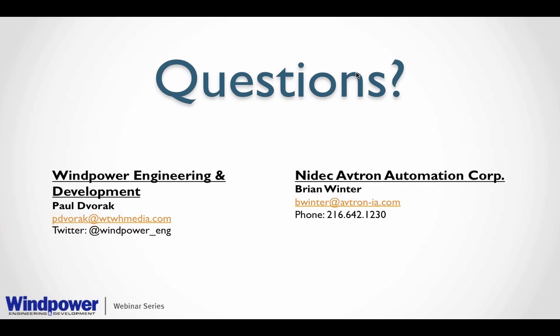Now on the electrical side, the E of EMI, what you want to do is have a design that's actually got a Faraday cage built in. For Avtron, we actually take the circuit boards and wrap them in copper foil. It's extreme because we want to make sure nothing can get in. You can have some extremely powerful radio wave fields. We were familiar with an example where a manufacturer actually installed some wind towers north of an aircraft radar installation, and they could actually see the radar towers from where they were installing the towers. And when the tower was pitching directly into the thing, they could actually jam the drives. If the door was open to the drive cabinet, there was so much E pouring in that the drive couldn't think. So you need to make sure you're very effectively shielded from both magnetic and electrical interference.